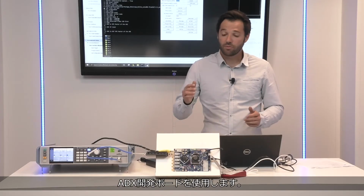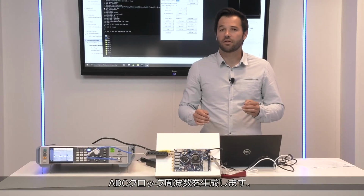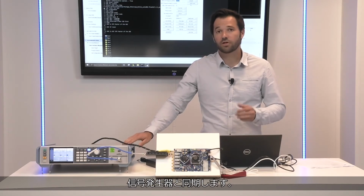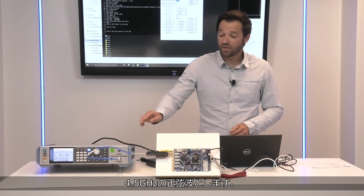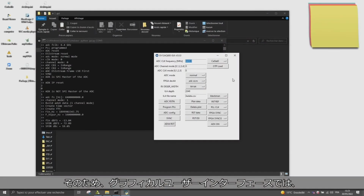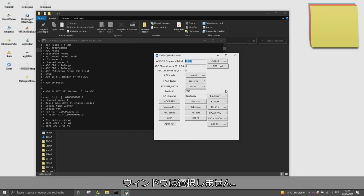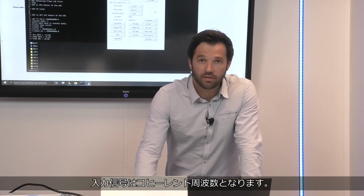For this demo, I'm using the ADX development board. The embedded PLL generating the ADC clock frequency is synchronized with this signal generator generating ADC input signals. Here, a sine wave at 4.5 GHz. So, in the graphical user interface, I have to select PLL external reference, and no window, as the ADC clock frequency and input signal are coherent frequencies.